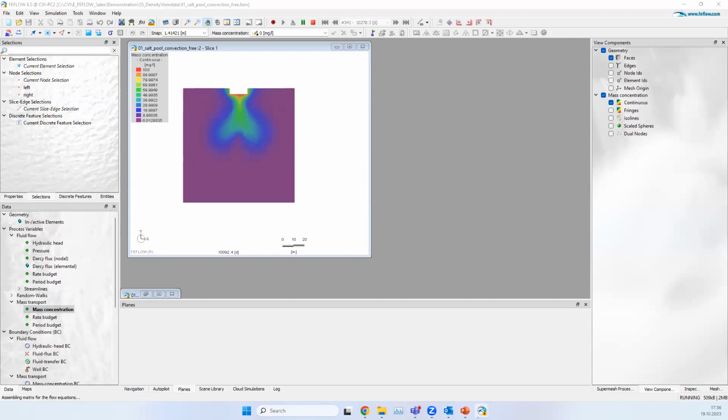And then there are a number of questions here. I'm doing a seawater intrusion modeling using FEFLOW 8. At the moment, I have several questions. Okay, in the sea level rise simulation for the mass boundary condition at the coastal boundary, should I assign a mass BC of first type or second type? I mean, if you know the concentration, you will assign a first kind boundary condition equal to the concentration of the seawater.